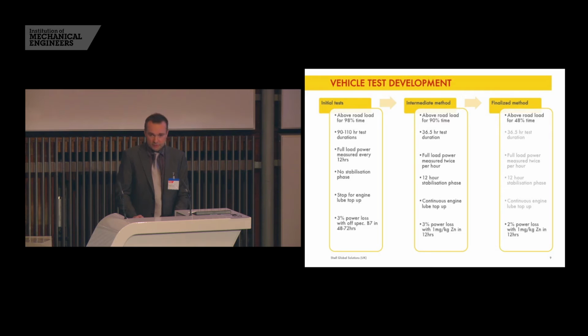The tests were very long duration, around the 100 hours mark. We only measured full load power every 12 hours. There was no stabilisation phase included initially, so we allowed a basic engine warm-up of about half an hour before we went straight into the dirty-up phase of the tests.